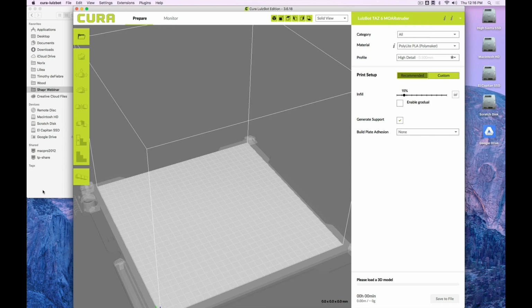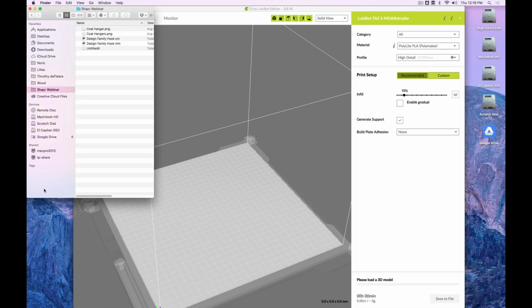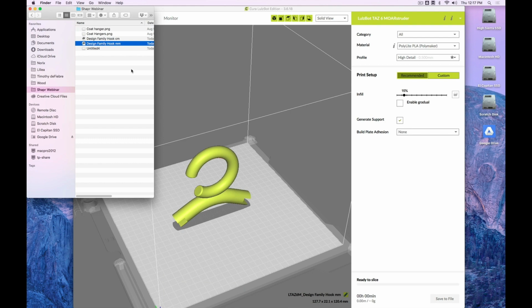And there's one thing that's really important for you to keep in mind, and that is in Shapr when you export and what dimension system you export when you go for STL, because mesh models don't have the scale built in. So I have here a millimeter and a centimeter version. So I drag in the millimeter version, and you see this looks good. I drag in the centimeter version,